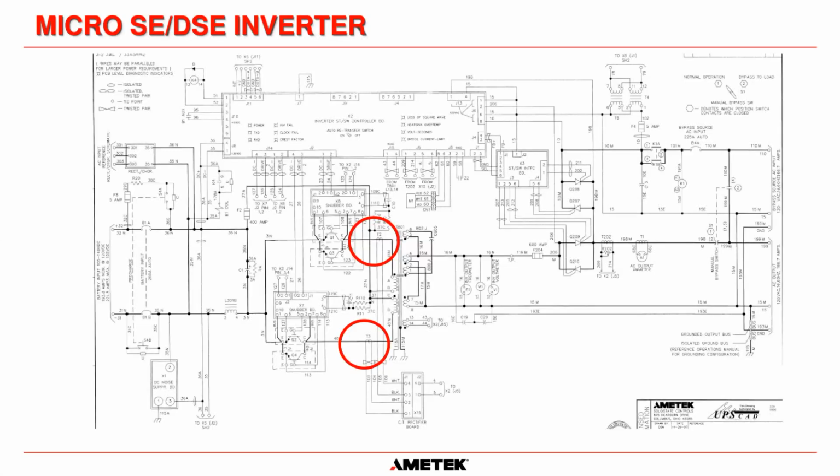Okay. If we had a short circuit on the output, if something on the load had a short circuit and live to neutral was connected together, then we can't regulate that short circuit current. So the IGBTs will try to supply over 100 amps.